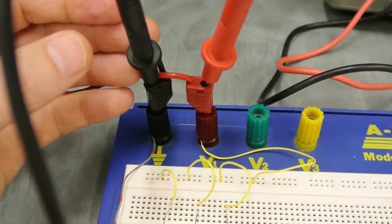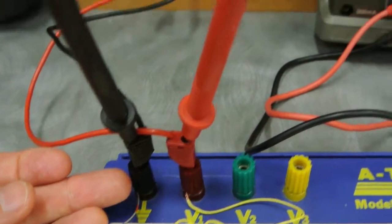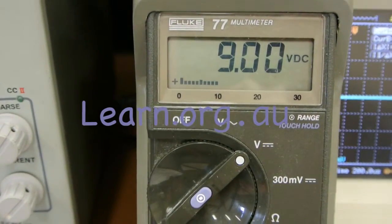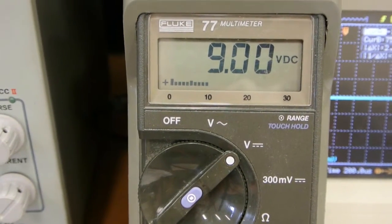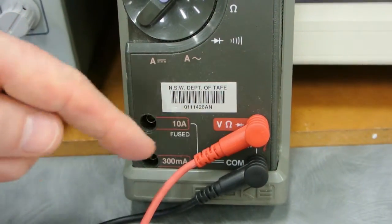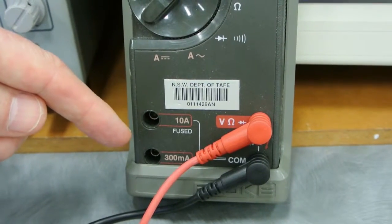Just as we've done previously, the very first thing to do is confirm that we have the 9 volts at the supply part of the circuit. So you can see there, 9 volts. I've used the Fluke multimeter to confirm that is the correct voltage before we go ahead. Now I'll have to move the leads on the multimeter from voltage to current, and then we'll proceed to do what's set out in the lab, and that is to measure the total network current.